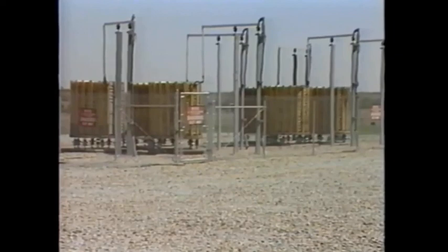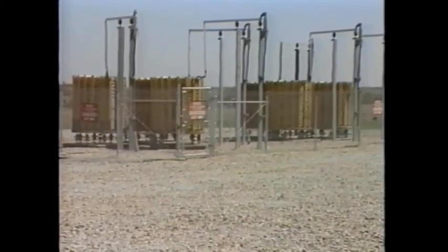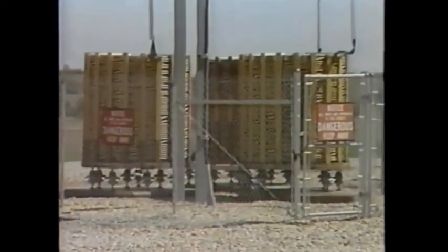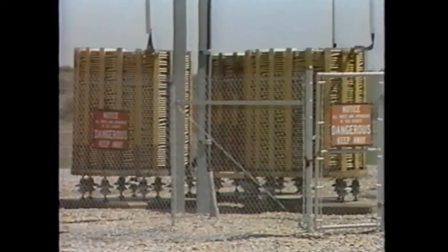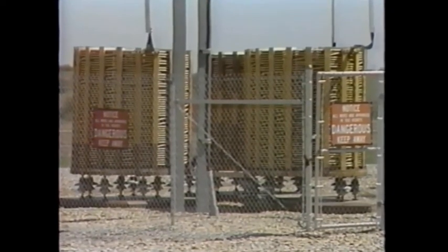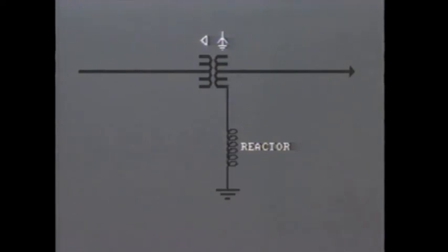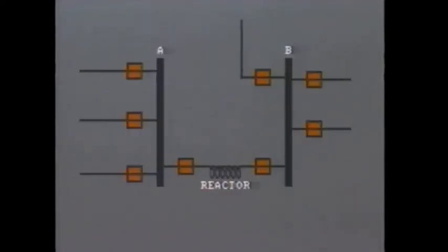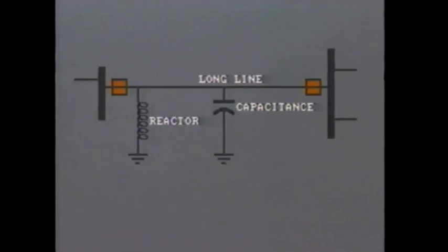Now at this point, let's extend our overall view of transformer protection to include reactors. This is because there are many similarities in construction and therefore protection is also similar. Generally, reactors are air-cooled or oil-immersed single or three-phase windings on an iron core. Where is the reactor installed? Well, typically in a grounded neutral to limit fault current, between buses to reduce magnitude of current flow, or shunt connected between line and ground to compensate for capacitance on long lines and prevent high voltage levels.